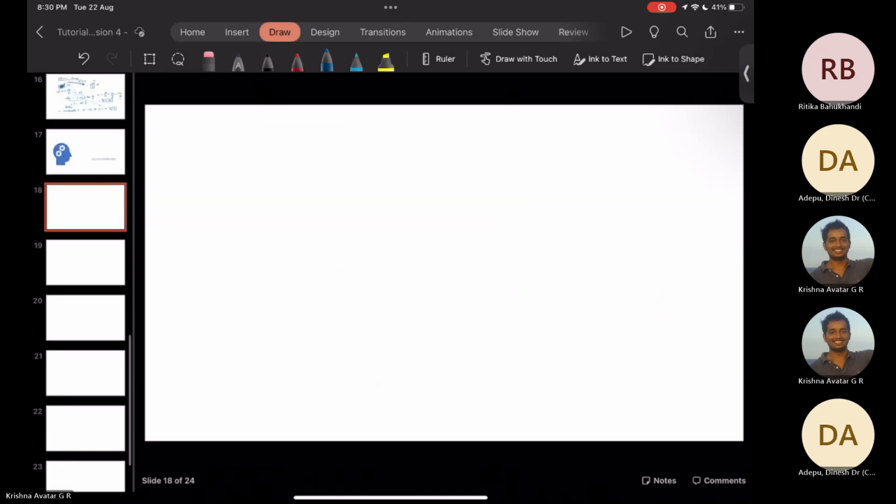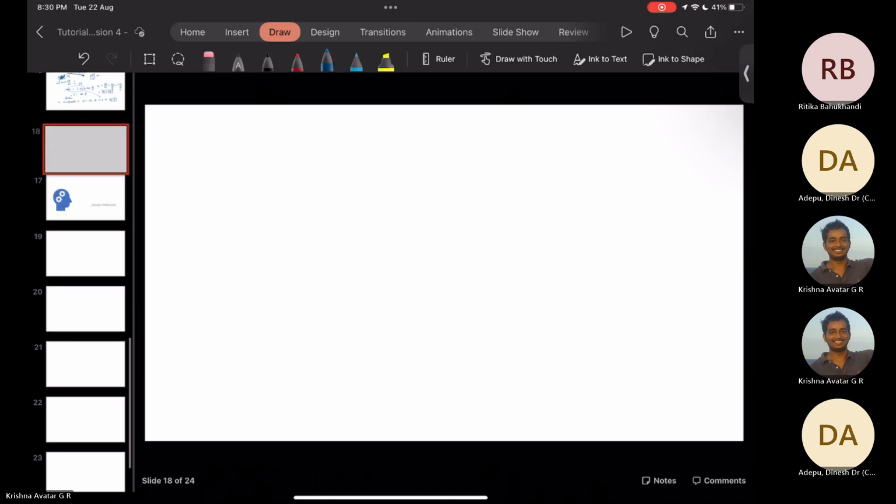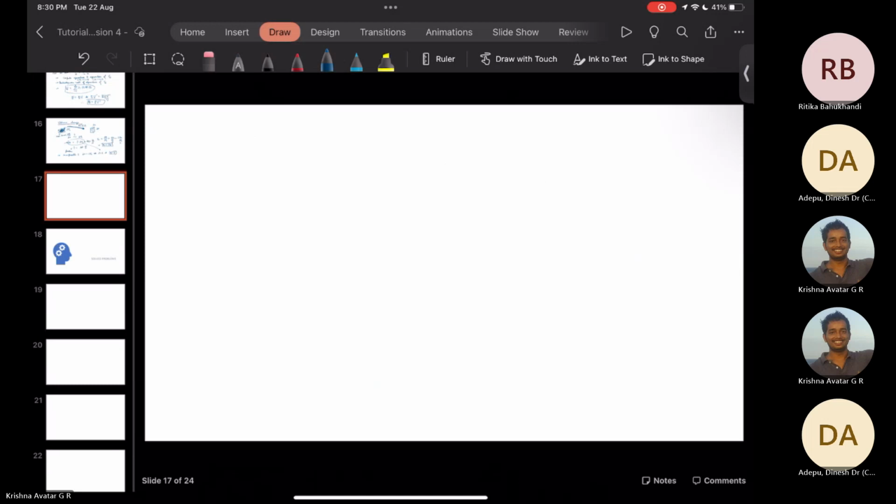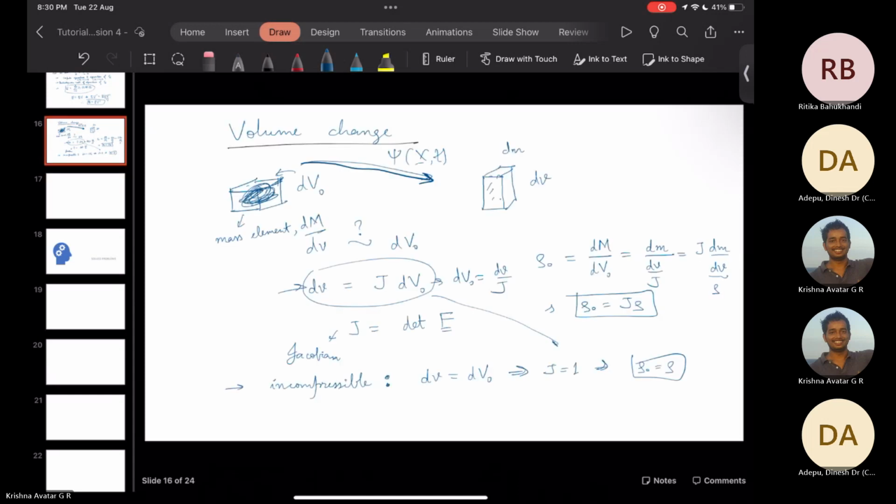And I'm sure that in fluid mechanics there is a difference between incompressible fluid and incompressible flow. We'll not talk about it here, but there is a difference between these two terms. Only for incompressible fluid do we have this relation. However, even for compressible flow, under certain considerations, we can still have the flow be incompressible. It's just some adjustment and some particular relations being satisfied.